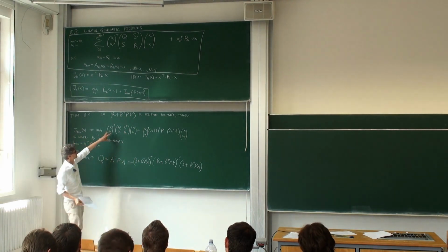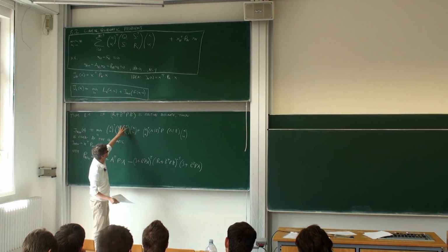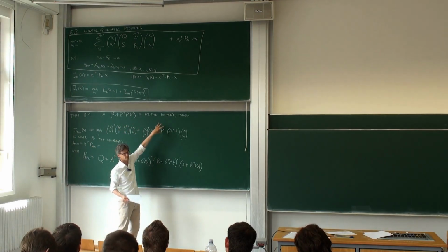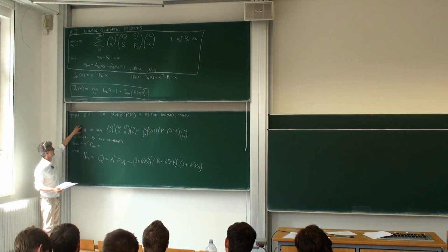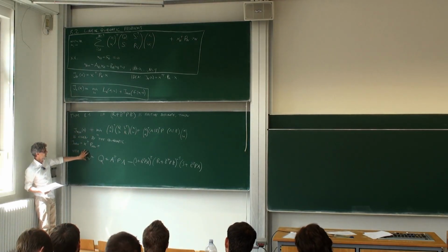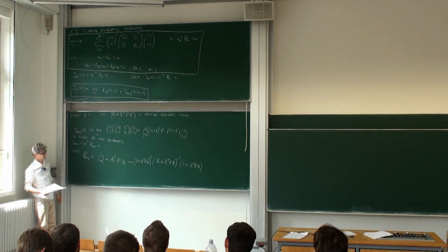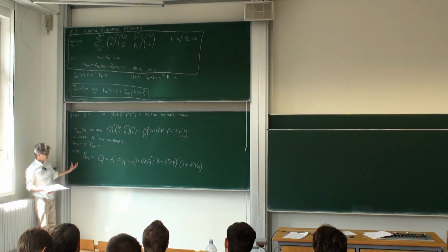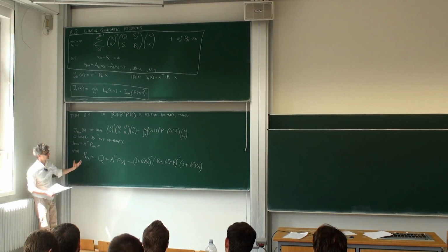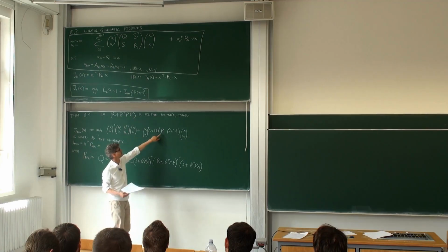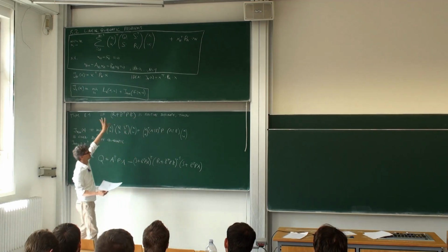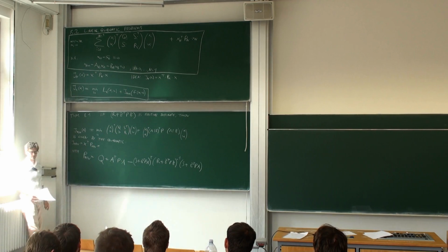So if you have this quadratic function, which is the sum of the stage cost and the cost to go, then after one time step, if you minimize over u, this is giving you a new quadratic function, and the matrix you can even compute by this expression. Of course, I could add all the indices. I would call these things all index k here, here would be a k plus 1, and then I would actually just get the algorithm, but you will not see the blackboard after all these indices anymore. So I omitted them for a moment.